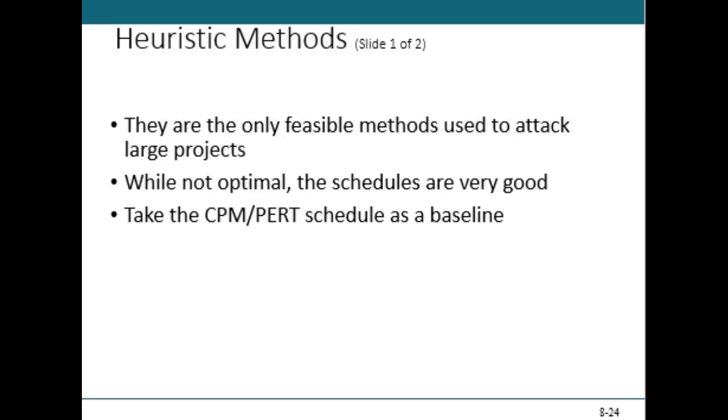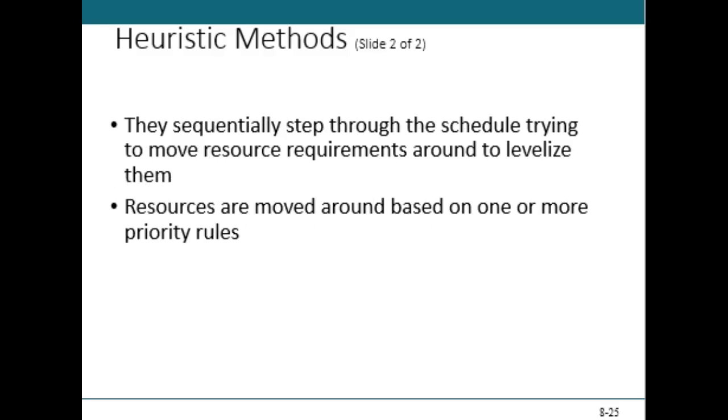And so scheduling by this rule is accomplished as follows. When activities compete for resources which are not available in sufficient quantities to schedule all the activities simultaneously, we schedule those activities with the least amount of slack or total float as determined by our critical path problem.